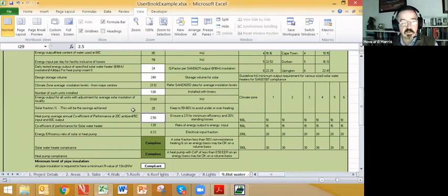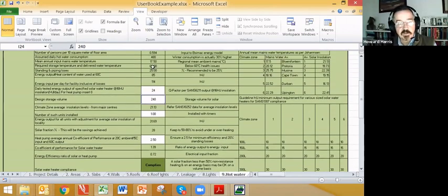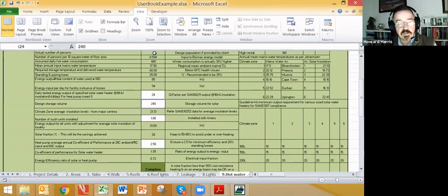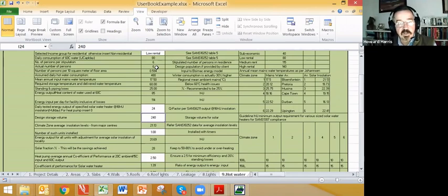Many are the instances where the solar fraction is dreadfully low, 28%, and you can see that if we were to increase this beyond, incidentally, this 240 would be the statutory minimum size for a 6-person, 3-bedroom house, because it would be 6 persons times 40 liters per capita, as per table 5 of SANS 10400-XA.